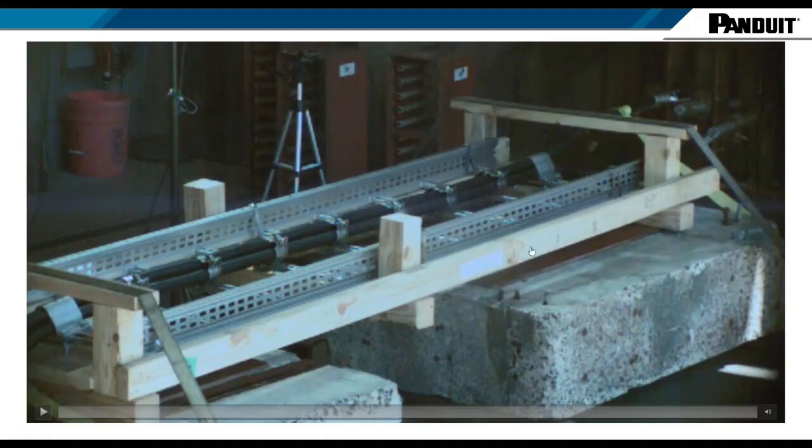So we'll put through it 1 kV, all 3 phases to earth, 1 kV AC or 2.8 kV DC for 2 minutes. If we hold that voltage, then we can assume that there is no damage to the jacket where we can't see it within the cleat, and we get a category 2 test.